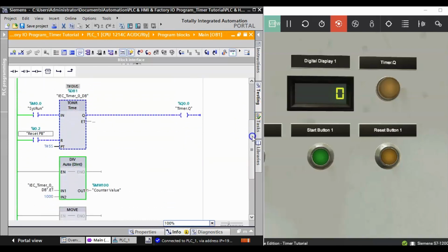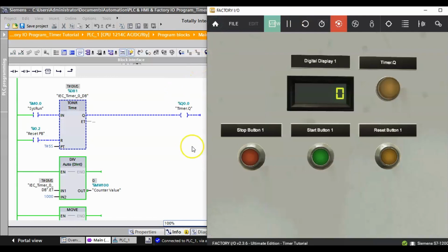Very nice. Okay, so we'll take a look at this guy. Remember that these guys are all the same throughout. The 3-wire and the division and the move have been the same, and all we've been doing is literally clicking on the timer and changing it to an off delay, a pulse, or now a retentive timer. Okay, so this one should hold the value.